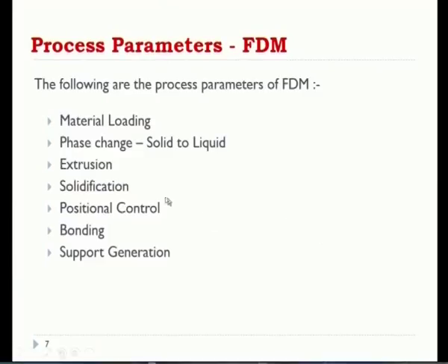So what are the major parameters involved, like how to load the material, that is also a role here. That's why I mentioned here material loading, phase change, that is liquefaction and extrusion, solidification, position control, bonding and support generation. These are all the major parameters related to fused deposition modeling. In detail we are going to discuss each and every parameter.